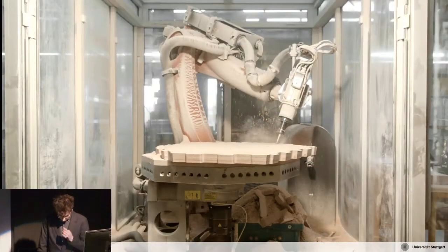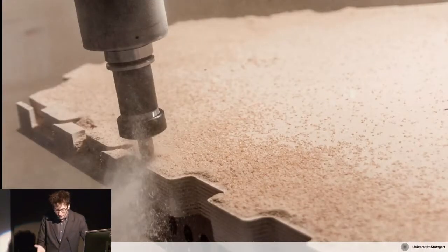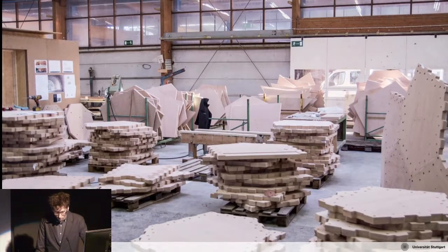Of course, that's not how it looks like. This is more how it looks like. It's really also a messy kind of work that you have to engage with. But you have to, as an architect, and we are architects, you have to engage with the machine. You have to understand how milling works, for example. You have to understand what kind of milling tool you need, what diameter it has, what is the speed of the spindle, and so on, and what's the outcome later once you mill it, what's the surface quality, what are the tolerances that you have. Especially with this kind of construction, you really need the material, the finger joints, to touch so that they can transfer the forces later.